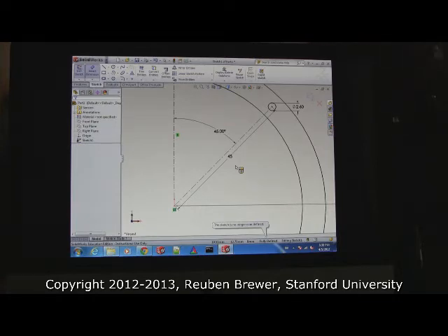Let me stand corrected. Every single error I've now seen on your guys' laptops is because you're not zooming in far enough before you select things. And it's okay. It happens to me on a daily basis, but you zoom in. You can zoom and unzoom with Z and capital Z too.